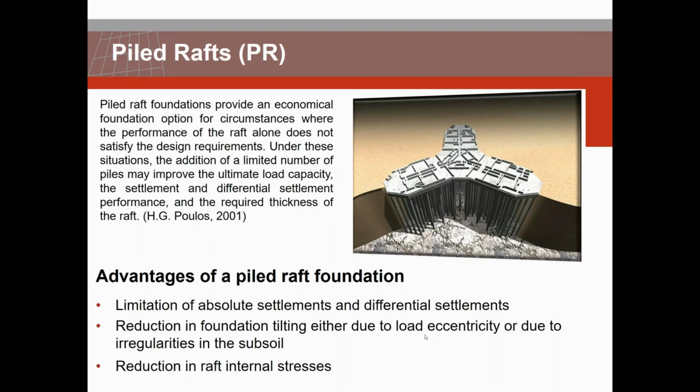Next to pile groups, we have pile rafts. Pile raft foundations provide an economical foundation option for circumstances where the performance of the raft alone does not satisfy the design requirements. Under this situation, the addition of a limited number of piles may improve the ultimate load capacity, the settlement and differential settlement performance, and the required thickness of the raft. This is a statement from Poulos.